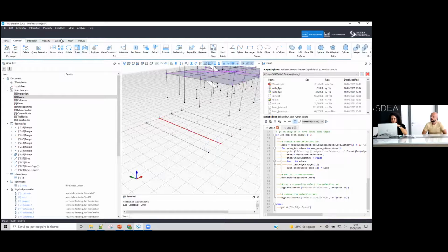Just remember that when you have an overlapping thing and you want to copy it, you have to select it from the list first. So like this, you will just copy one. But if you select, for example, with this kind of selection, you will have both. So if I move this element here, I have moved both of my lines. So whenever you want to select overlapped geometries, you just use the click on and not the rubber band.